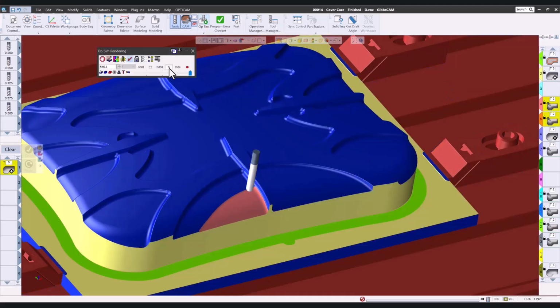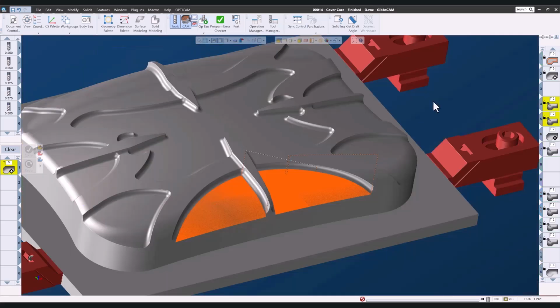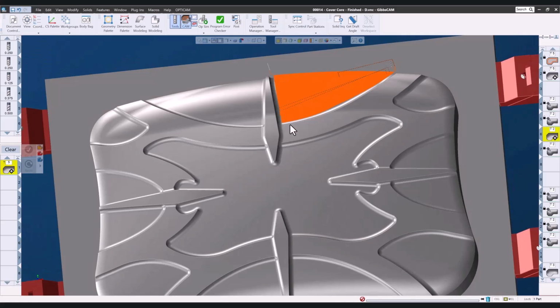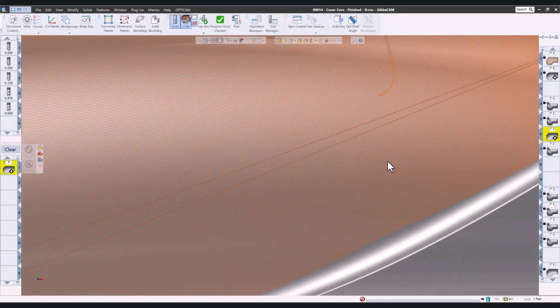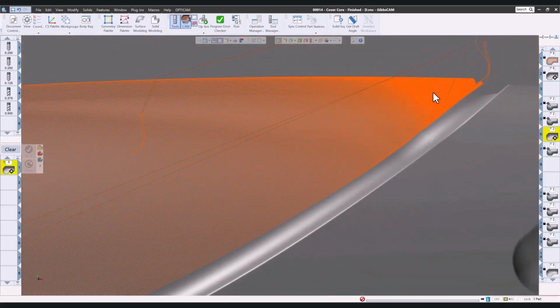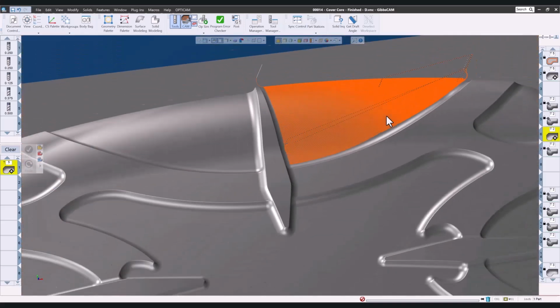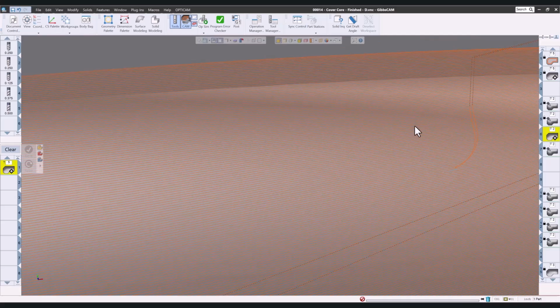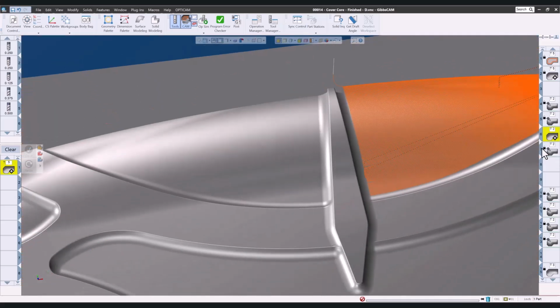You can see that this toolpath is running parallel to only the back curve, while this one is running parallel to both the back curve and the side curve. For this one on the back side, I chose an advanced 3D in-curve flow. I extracted edges from the model and adjusted them slightly and ended up with this. This looks good, except to me the toolpath gets a little too dense for my taste over in this area. Now we could modify the curves and get most of that out, but just taking one shot at this is what I ended up with.